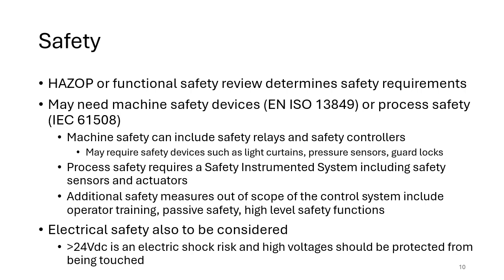So if you've got an operator who's loading a machine, they could be loading the machine every few minutes. You need to have appropriate safety to stop the machine from operating while they're loading the machine to avoid any physical injury from the machine operating. And they could be loading the machine quite frequently, unloading the machine quite frequently. And that can also include guarding on cells, guarding on any entry into the cell itself. Also maybe that could extend to things like robot safety and so on. But the idea is it's safety that needs to operate quite quickly to stop injury to an operator, but also has to operate quite frequently.